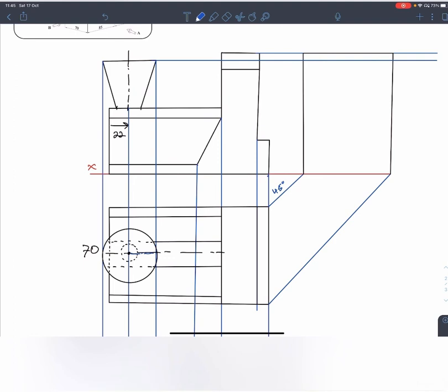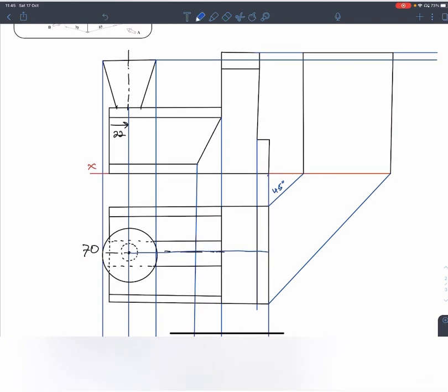Now, how I bring across the center point is, remember when I was telling you that it's no good if I draw my 45-degree line from here, because it's not going to connect up. I know some of you are doing that sometime at some stage. Okay, what I need to do is I need to bring it out to the extreme point of my object and then draw the line at 45 degrees. Bring it out to my extreme point of my object and then draw it out at 45 degrees. Okay, so that's there done now again.